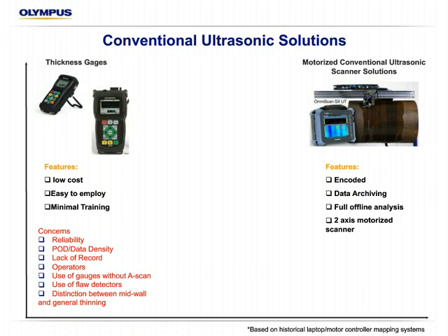So at a minimum, if we can make any recommendation with thickness gauges, if you're looking for corrosion or you're in the in-service market, is that you at least get a quality thickness gauge with an A-scan or waveform presentation, so it gives the operator a little bit more to go on to make the correct distinction. There's also a big trend to use flaw detectors in lieu of dedicated thickness gauges, or something you might go out and do a shear wave examination with, and then you just put a 0-degree transducer on it and try to take precision or accurate thickness measurements.